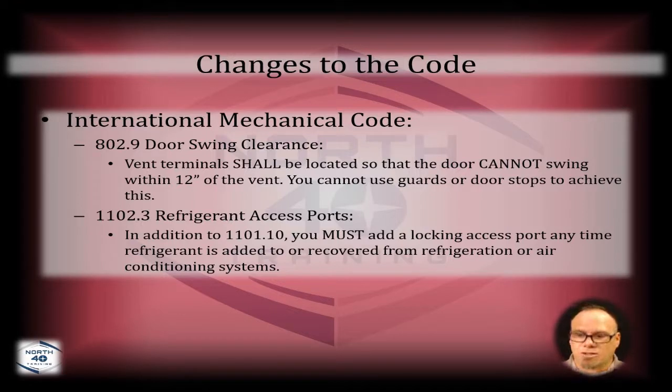Many inspectors tell you that if you're putting your hoses and gauges on there, there's an exchange of refrigerant, and when you're done, it's got to be up to current code. Now, refrigerant access ports, having the locking access caps on there, has been a really long process because it's changed so much. Right? If you would have looked at this in 2009, it said any refrigerant containing vessel has to have a locking access port cap.